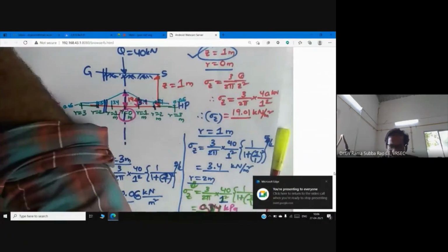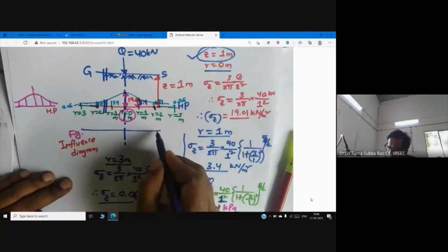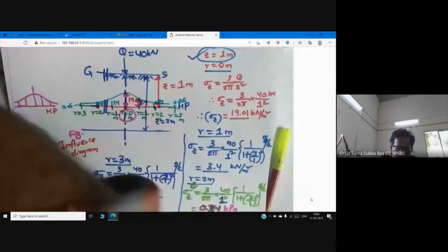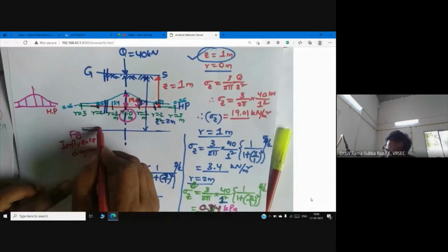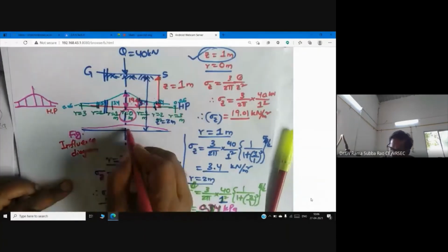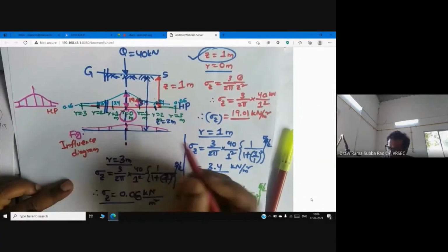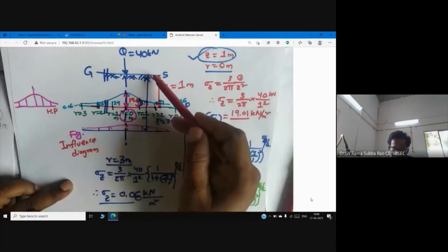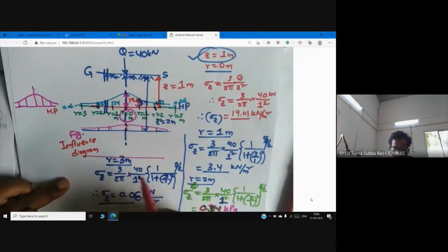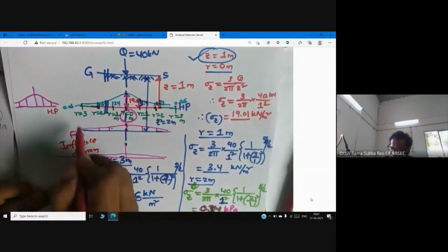Okay, with this understanding, what can I ask you? So now you need to calculate vertical stress, and Z is 2 meter. Then I can tell you how the answer comes. Then you will ask, sir, why did you draw it so big here and small over here? Then what I say is just one thing, I am going farther away. I am very far from the load now as compared to 1, 2. So that means, a moment you see, when Z is 10 meter, it is almost like a straight line.